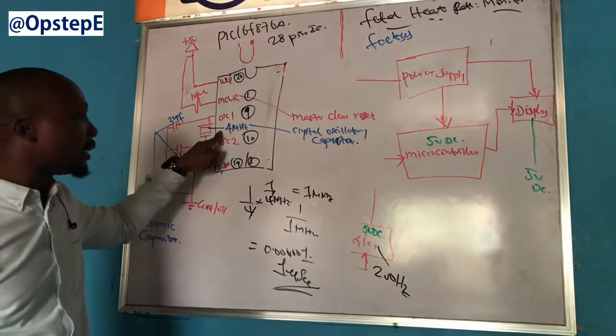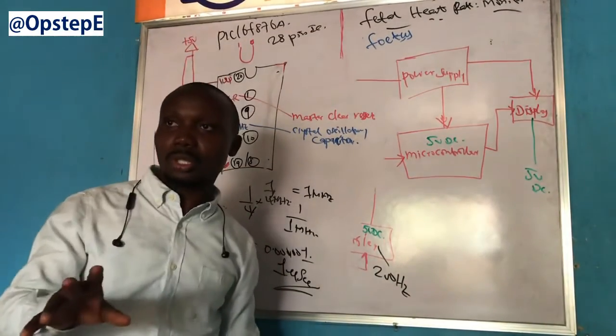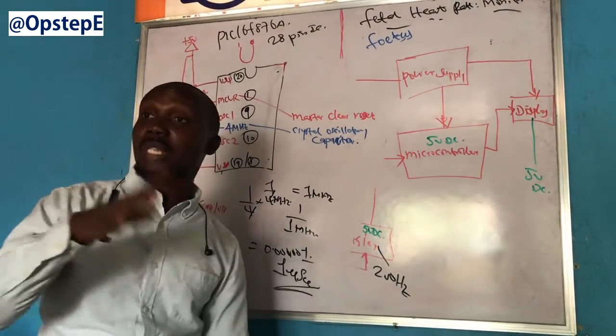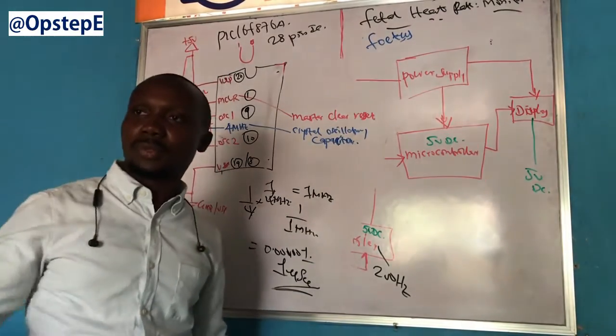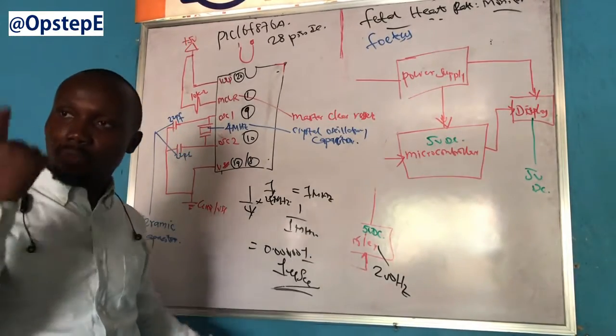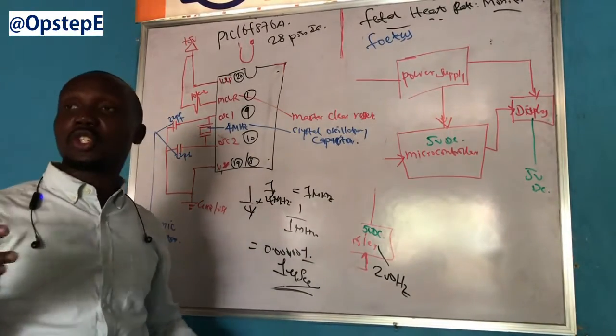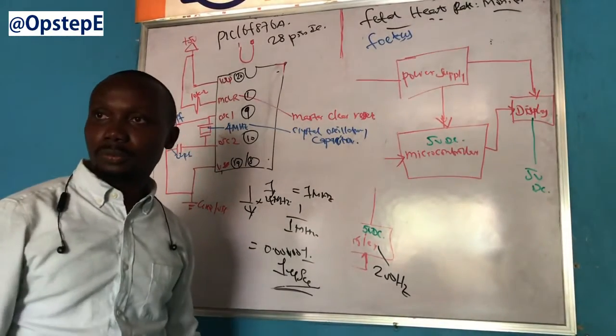Whatever value that is there is what the system uses to execute single cycle instructions. Any instruction that is more than a single cycle is multiplied, this value is multiplied by the number of cycles. So if it's a 2 cycle instruction, then it's 2 microseconds for that instruction. If that instruction is a 4 cycle instruction, then that's 4 microseconds for that instruction.